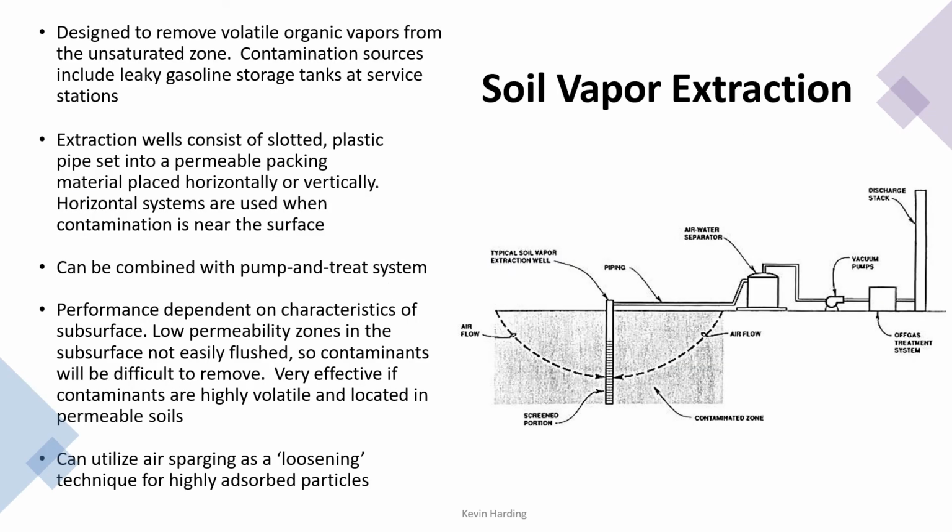The next system of how we could potentially clean groundwater, so water that has been polluted in the soil, is through soil vapor extraction. The idea here is that this contaminated zone is the gray section, the darker shaded bit that's there. We pump air through the soil and push any of the contaminated water into an extraction well here. There are perforations through this well, so any of the pollutants go into this well. It then gets pumped up, and it can then get discharged or sent off or treated afterwards.